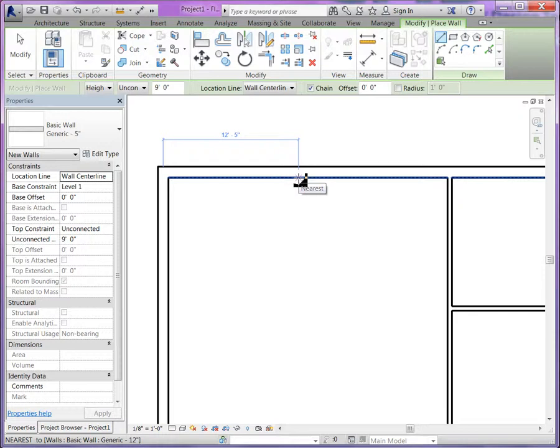You can see to the exterior wall, it's in the center, right? And it's going to be to the center of the interior wall that I'm going to draw. You got 6 inches there. You got 2.5 inches for the smaller interior wall. So you got to take that into consideration, plus the 10-foot space that you want to create there, right? So we got 10 feet, 8.5 inches, right?